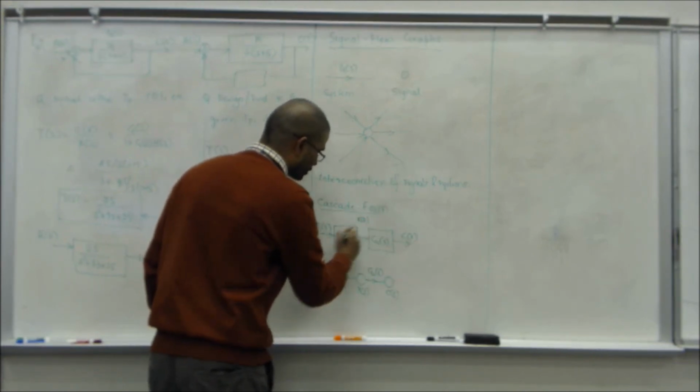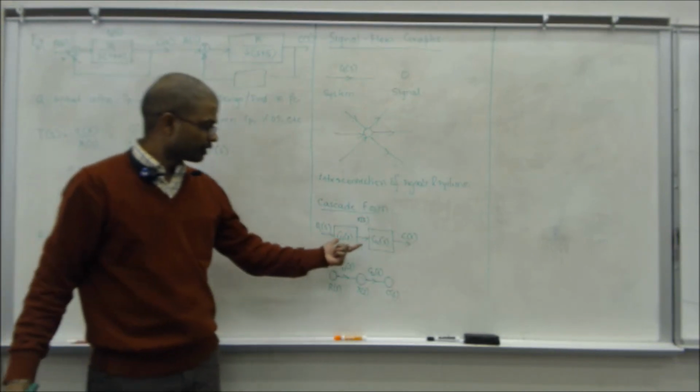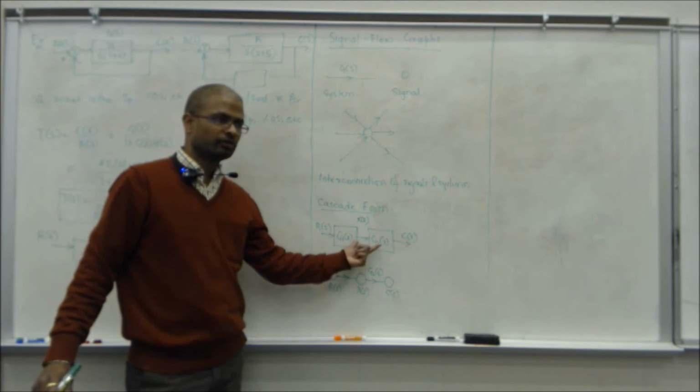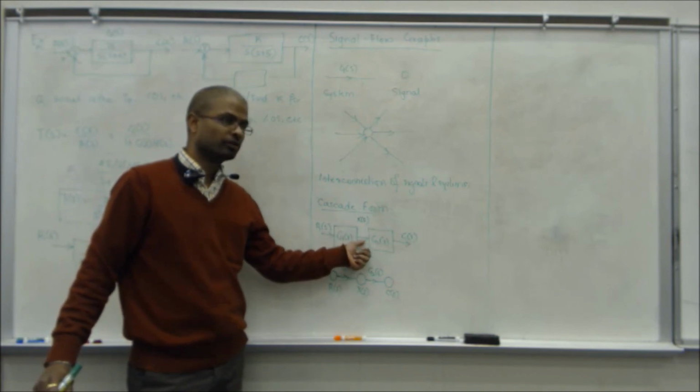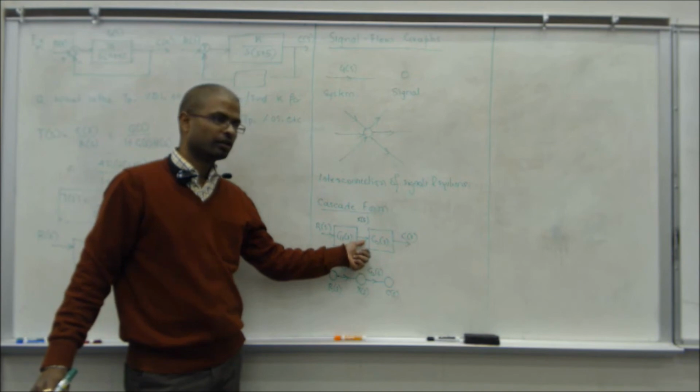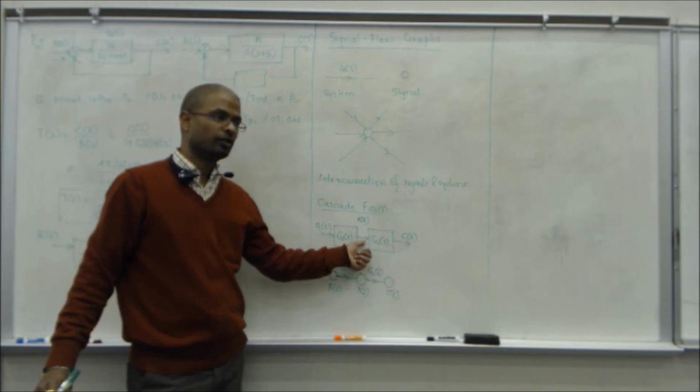No, there is a different signal. But what I'm saying is, if you're looking at block diagram reduction, if you ignore that there is a different signal coming here, there is an X of S. If there is no X of S, you just assume or you put a value, you denote that signal by something else.